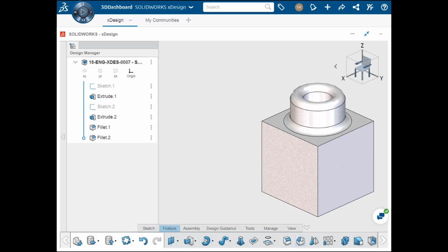Chamfers are another feature that's similar to fillets. Chamfers create an angled face along an edge as opposed to a rounded face created by a fillet. Chamfers are often used to break sharp edges as well, but they provide a different aesthetic and are typically easier to manufacture. One function of chamfers is creating a locating feature for objects to slide within a cylindrical hole.